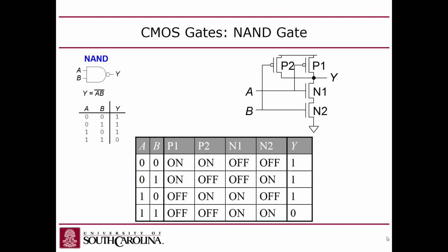You guys with me? And then once you build your NMOSs, then you just build the PMOSs as whatever the reverse of these guys are. So in this case, because these guys are in series, these guys would then be in parallel. Make sense? At least that's how I do it. Maybe that's the way I've always done it, right?